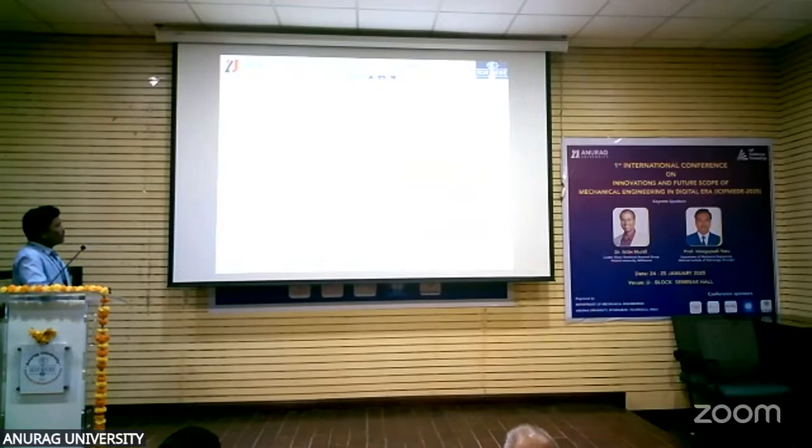So the main effect plots for the tool wear and surface roughness values. In tool wear, the voltage is the main influence parameter. Coming to the surface roughness, the pulse on time is the influence parameter, followed by the current.